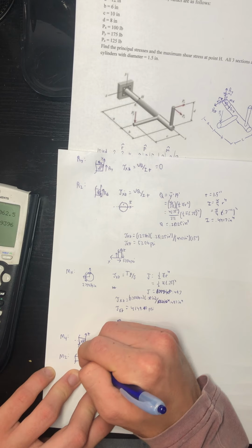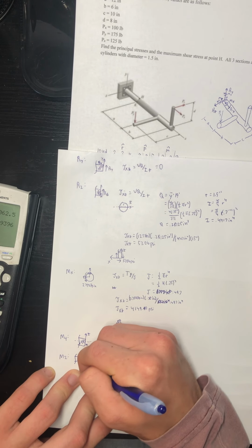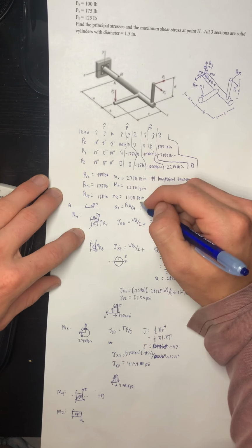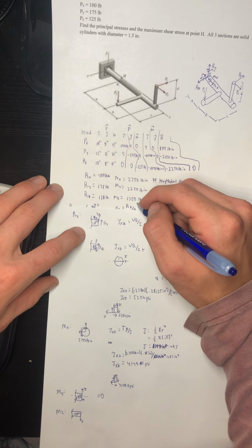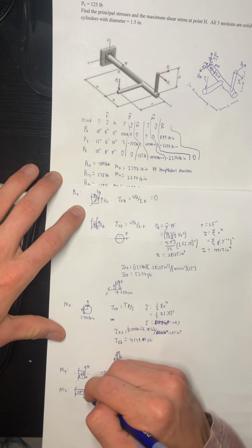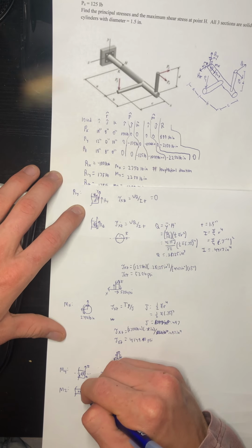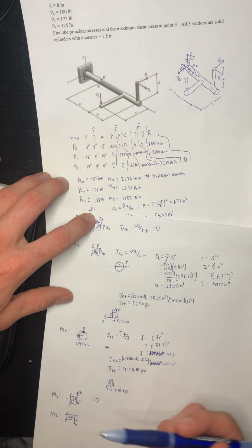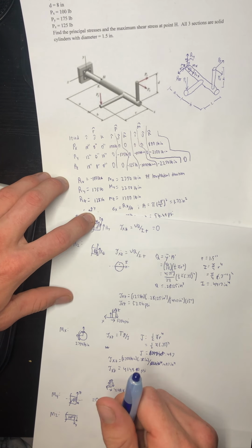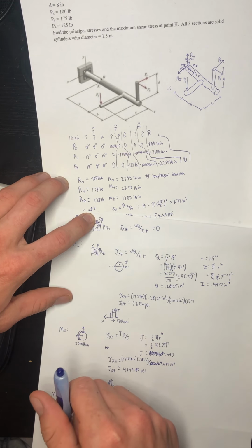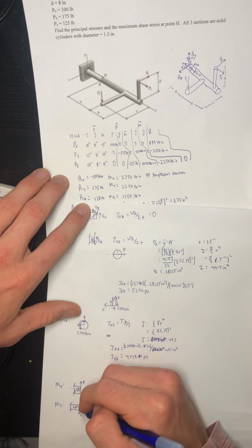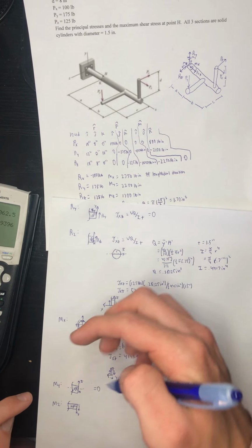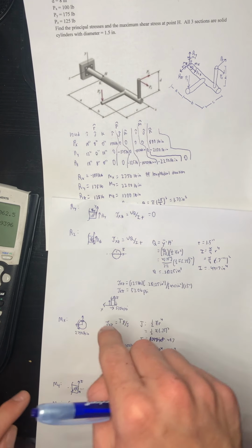Okay, X and Y. And this bending is, let me see here, positive 1300. So we're going to be looking this way since we are looking at this. If X is going to the left and Y is going down, then that means we're looking down the positive Z axis. X is going to the left, Y is going down. We're looking down the positive Z.